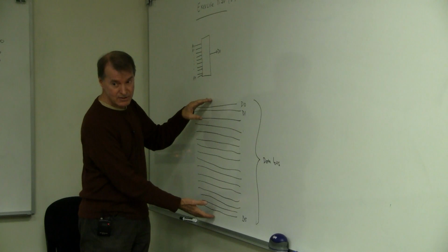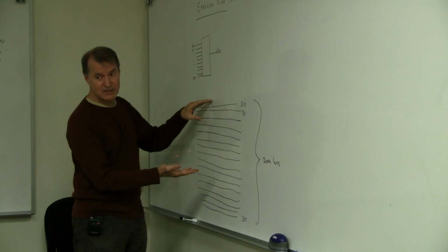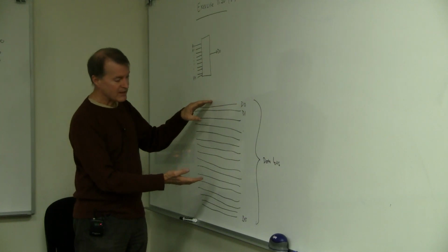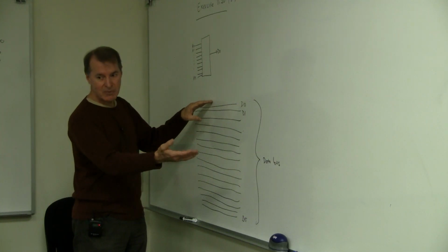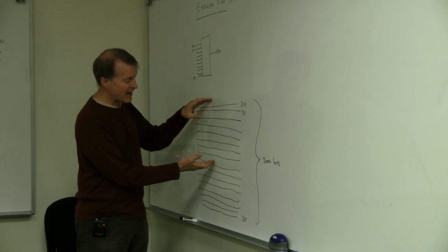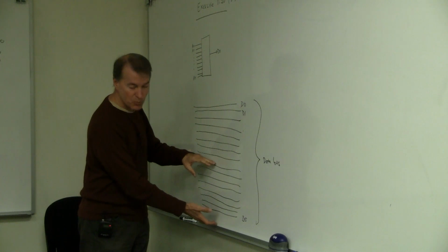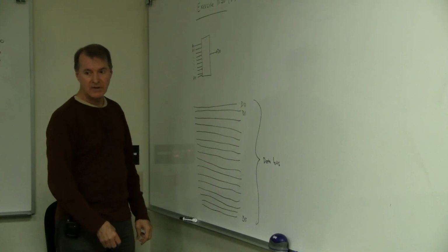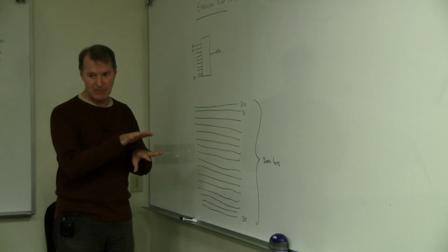It's 2 bytes. So when the CPU requests data from some address in memory, what does the memory subsystem have to put on the data bus? It puts the byte at that address and then at that address plus 1, in parallel, that is, simultaneously.